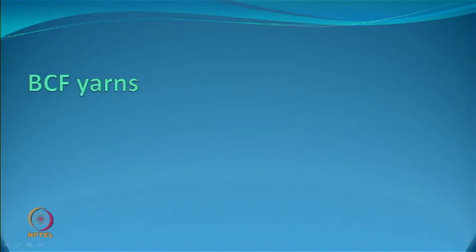Now what? So, we have a bulk yarn which is air jet, we have false twist textured yarn which is obviously stretch or modified stretch. This is something interesting, which we consider as technologies learning from each other, and that is how you had the BCF yarns, and they are also commercially very successful products, like false twist texturing and air jet texturing.